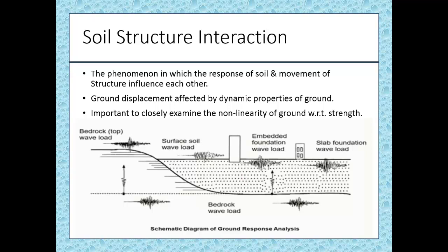And then the ground displacement, in turn, is largely influenced by the dynamic properties of the ground. And also its modeling method is influential. The ground then exhibits a complete non-linear behavior depending on the strength developed in the ground due to the dynamic loading, and it is therefore important for us to closely examine the non-linearity of the ground relative to its strength.